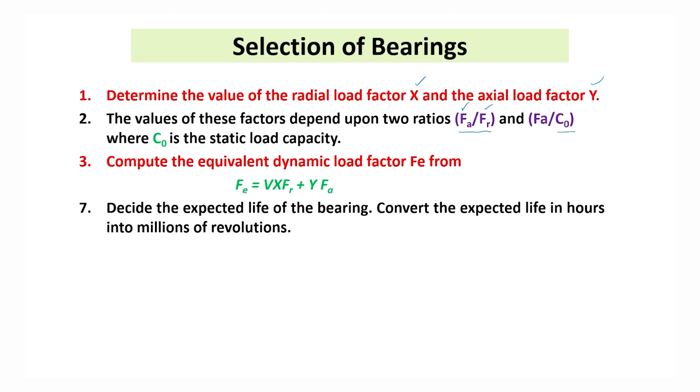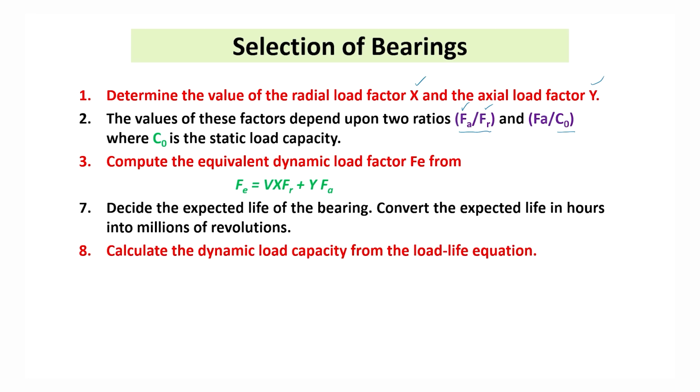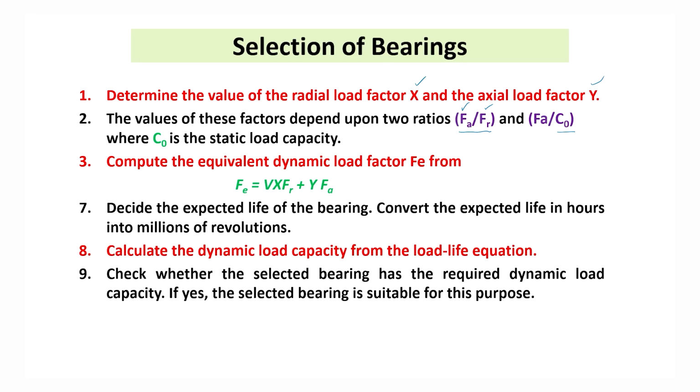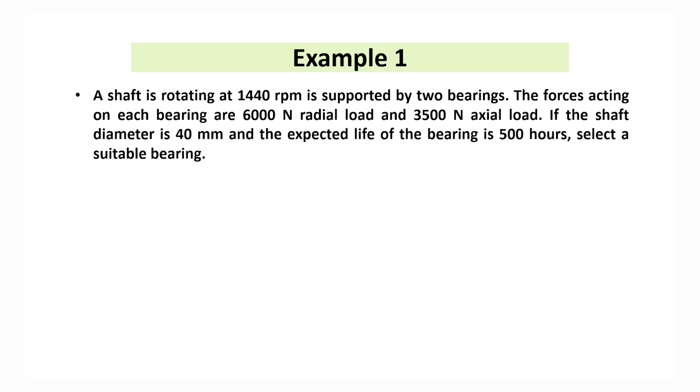Decide the expected life of the bearing, convert the expected life in hours into millions of revolutions, calculate the dynamic load capacity from the load life equation, and check whether the selected bearing has the required dynamic load capacity or not. If yes, the selected bearing is suitable for this application. If no, then we will go for another bearing. So, let us take one example.